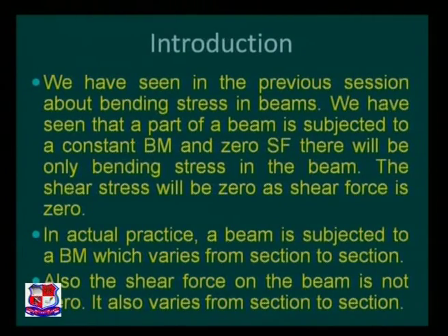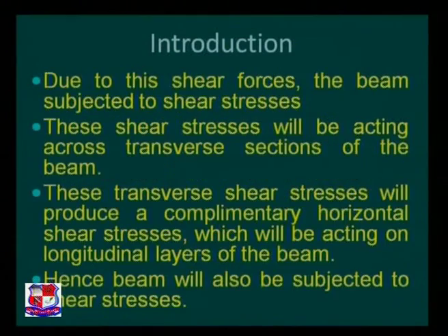It is important to note that in a beam the shear force always changes from section to section along with the bending moment. So we cannot avoid the word shear force. Due to these shear forces, the beam is subjected to shear stresses. These shear stresses will be acting across transverse sections of the beam.